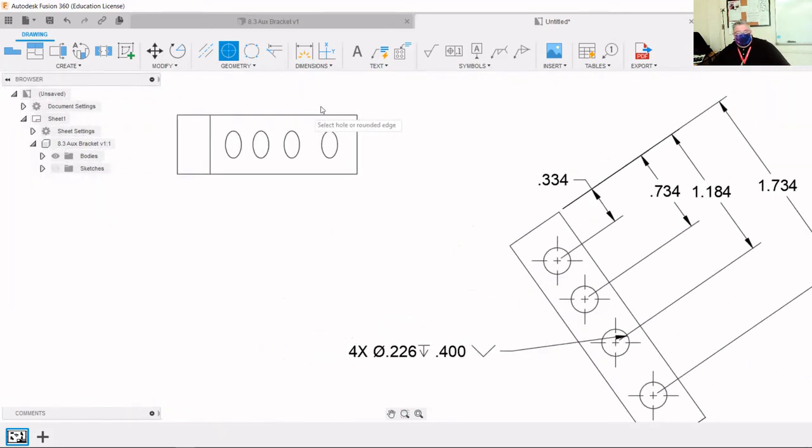You would have a lot of trouble, watch this. You'd have a lot of trouble dimensioning this. That top hole is not 0.19 from this edge. It's 0.335 or 334 or 6 or whatever it was. Like I said, all these end in 4, don't worry about that. But look at the discrepancy. If I dimension these holes using the top view, everything's wrong. That's why we have to have an auxiliary view.